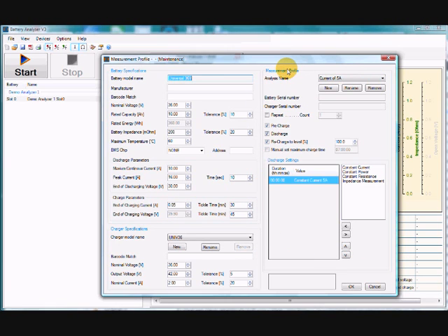The battery specifications show the voltages, capacity, and impedance criteria that the battery must comply to. The same goes for the charger specifications, the voltages and current that the charger has to comply to. Both battery and charger may be identified with the barcode on the battery and charger. This way, the correct profile is selected automatically. The barcode match field is used for regular expression matching.